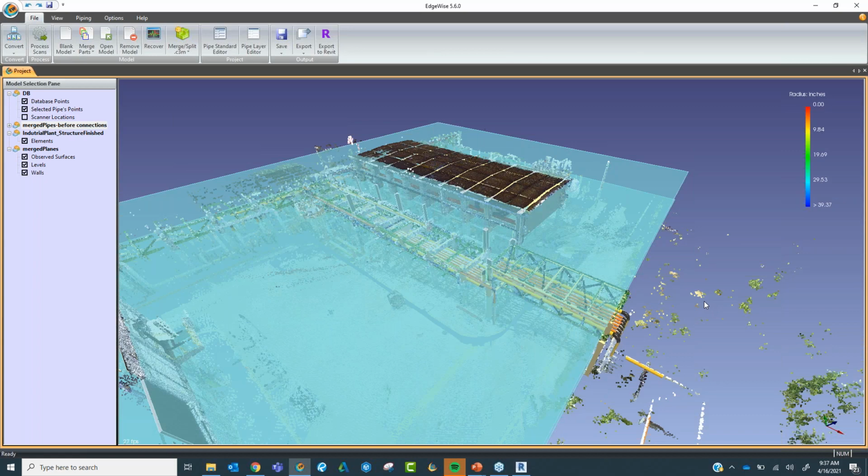But also that's kind of where we're looking at the unified data and how we can chunk these point clouds, breaking them down in ReCap, then bringing in a section of it and inserting that into Revit essentially, and doing chunks like that to help the processing time. Because you're right, if you get big models, let's say wastewater treatment facilities with a lot of pipes running through them, and you get that dense data, it's going to take a while to process.